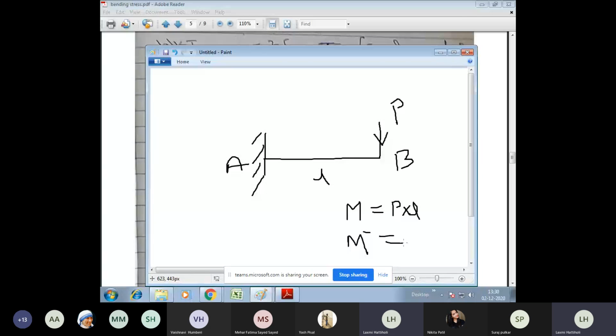So now you should understand the practical meaning of inertia. In the first year, you calculated the moment of inertia for all the sections, for rectangular section, I section, circular section. Maybe there you calculated it only in terms of magnitude. But now you should understand the practical meaning of inertia, right? Or you can take a scale. I hope everyone has a scale, either a 15 centimeter or 30 centimeter scale. Take a scale and bend it in both directions. Hold it in one direction first, apply some load and bend it, and hold it in the other direction also, and then try to bend.